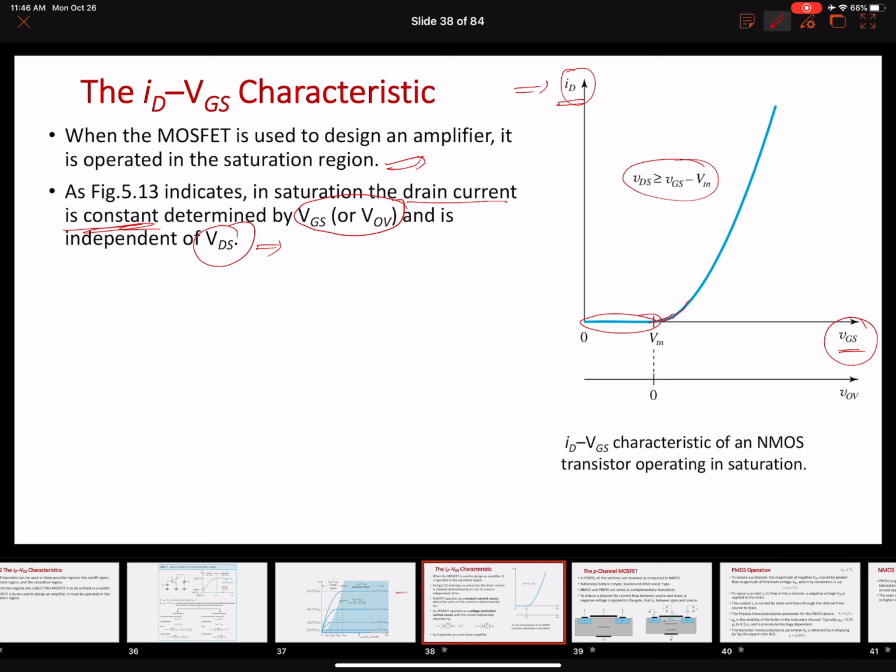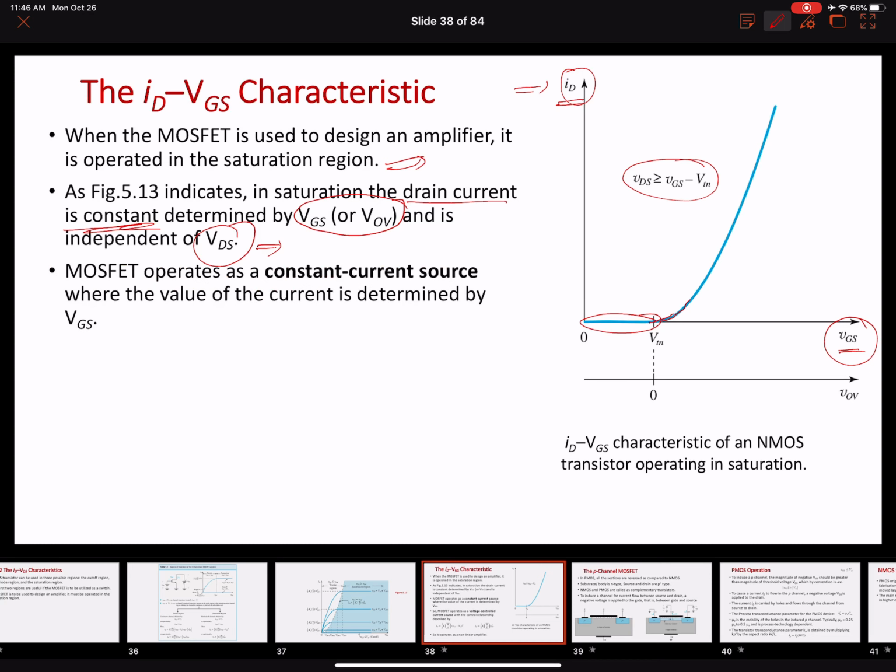Okay, and interestingly, you can see that it is not linearly related. We are going to talk about this concept in much more detail while designing the linear amplifiers. So what we can do is, for example, apply the input signal at the gate to source voltage, and as soon as it increases past a specific threshold voltage, a drain current will start to flow, and that will depend on the amount of voltage applied at the gate terminal. So we can build these voltage amplifiers. Okay, so we are going to talk about that in the next lecture in more detail, right?